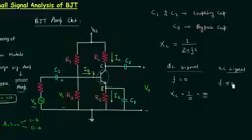In case of AC signal, frequency is not equal to 0, and I have already told you the capacitance for all the three capacitors is very high, and because of this the expression of reactance will have some large value in the denominator, and Xc is nearly equal to 0. So for AC signal, the reactance offered by the three capacitors is nearly equal to 0. The reactance is the resistance offered by the capacitor or the inductor.